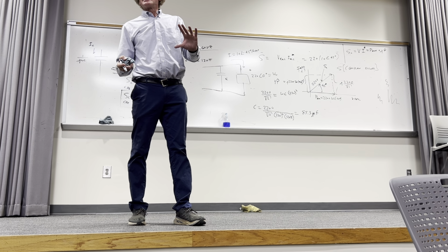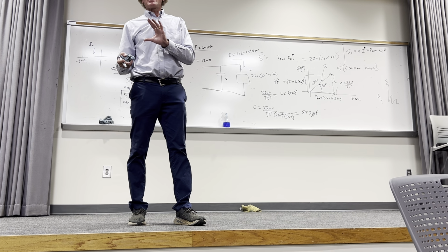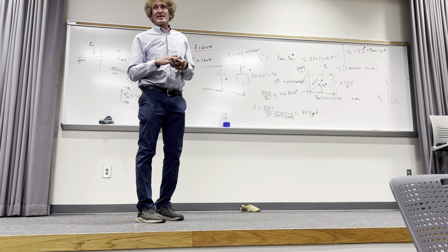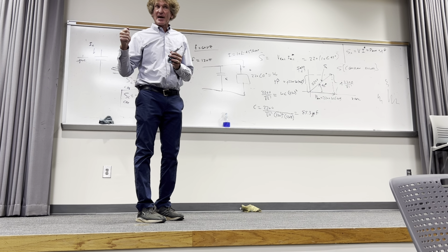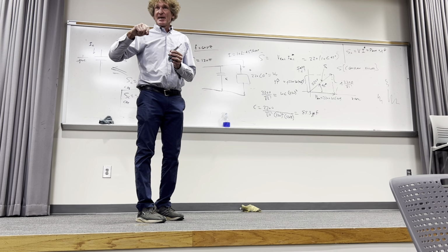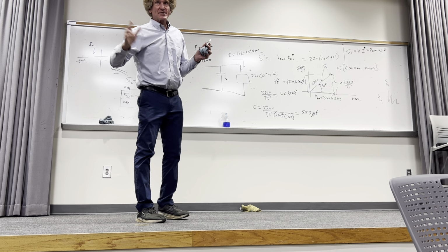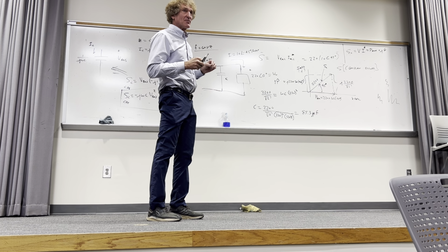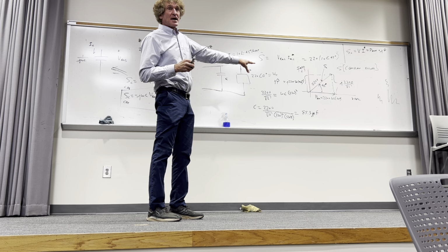No, it's not okay. At least double it, preferably go up by an order of magnitude if cost isn't too bad, because you have no idea the kind of crazy transients that happen on these things. From everything from lightning to when you break a wire and it's got a lot of current, wherever that wire is connected, it will get an immense voltage to try to sustain that current. I'm not gonna get into this too much, but just watch out for things like that. I've had my fair share of disasters because I didn't overestimate what could happen, or correctly estimate just how bad the transients could be. Anyway, you follow me on that, guys?